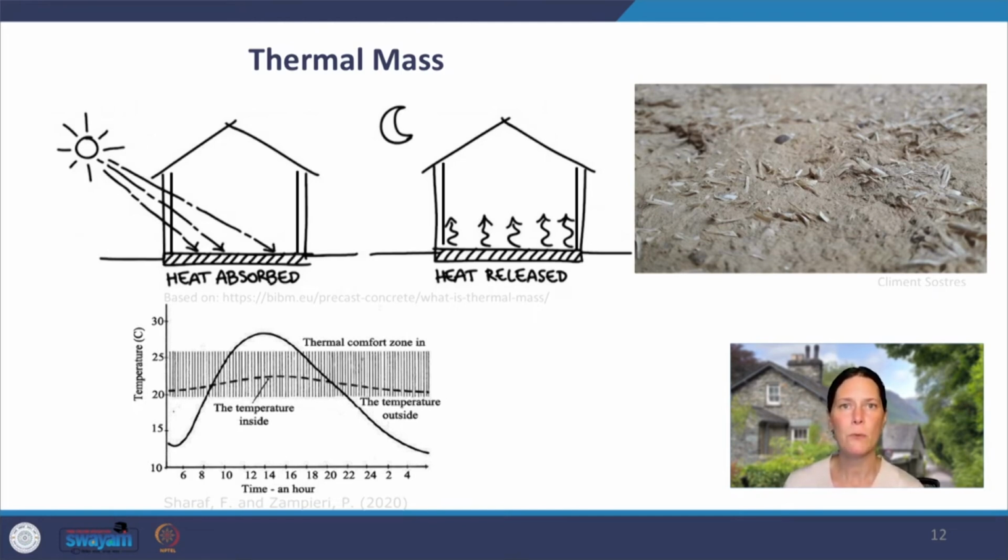In climates where the winter can be cold, internal fires will warm the walls on the inside, storing the heat. The straw in the bricks acts as some form of insulation. So using a brick ram or a press and compacting the soil slightly makes it less able to store heat. But again, wall thickness is critical to the equation of local temperatures.